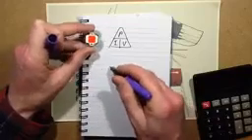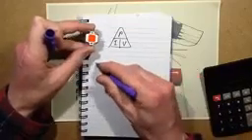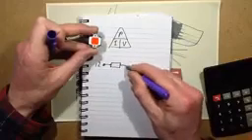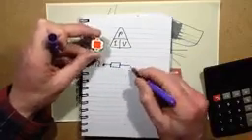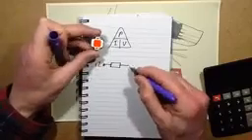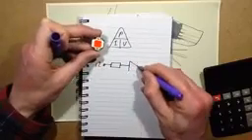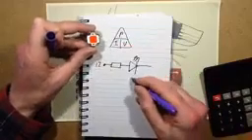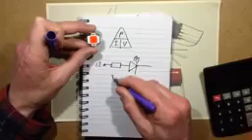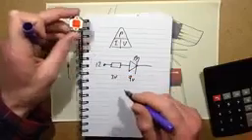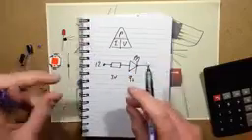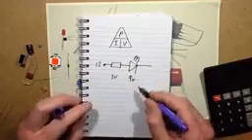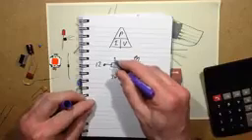So to calculate, if we were to actually put a resistor at 12 volt supply again, and choose a resistor to limit the current through this to the 1 amp. So let's see, I'll just draw it as a huge big LED. I'm not going to draw what's in it. There's a 3 by 3 array, but the voltage across that is about 9 volts. So we get 3 volts to drop across the resistor. And if we go back to the original formula, R equals V over I, we've got 3 volts divided by the 1 amp we need, so that's going to be about 3 ohms.